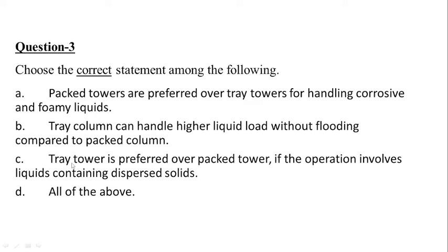So let's see option C. Tray tower is preferred over packed tower if operation involve liquid containing dispersed solid. So option C is correct, because tray tower is preferred over packed tower if operation involve liquid containing dispersed solids. This is because fine solids quickly clog in the pores of the packed bed.